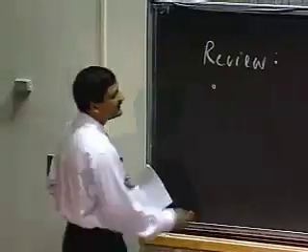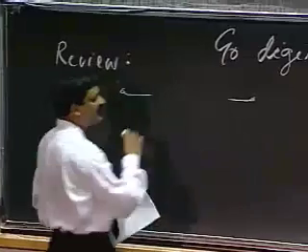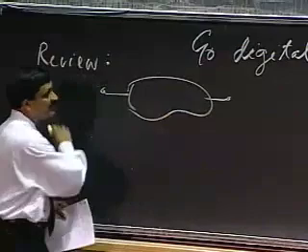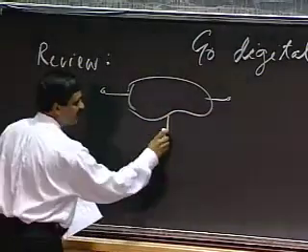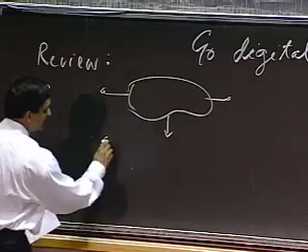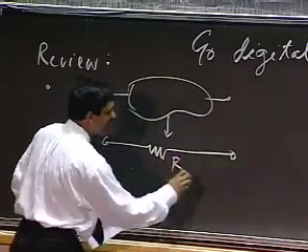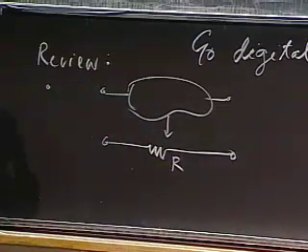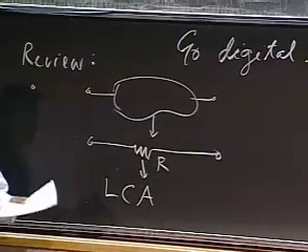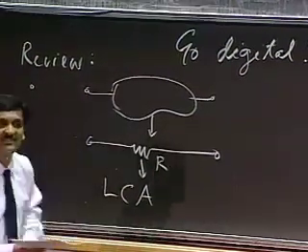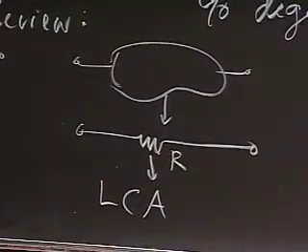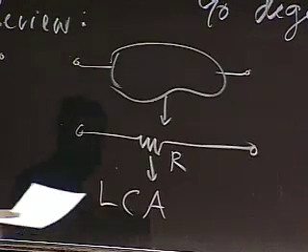In the first lecture, we started out by looking at elements and lumping them. For example, we took an element and said, for the purpose of analyzing electrical properties, let's lump this element into a single lumped value called a resistor, R. And this led to the lumped circuit abstraction. The lumped circuit abstraction says, let's take these elements, connect them with wires, and analyze the properties of these using a set of analysis techniques.